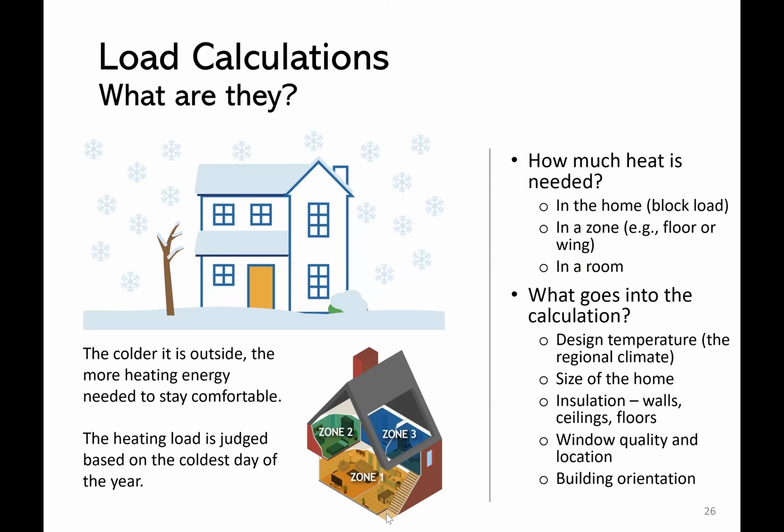Heat always flows from high concentration to low concentration, or thought of another way, from a higher temperature to a lower temperature. During the cold months, when the indoor space is kept warm, heat is flowing through the building envelope to the outdoors. The heating system has to be sized and designed to replace the heat that is escaping through the building envelope. Therefore, heat, or thermal energy, must be added to the air inside the house in order to maintain occupant comfort and favorable indoor environmental conditions.